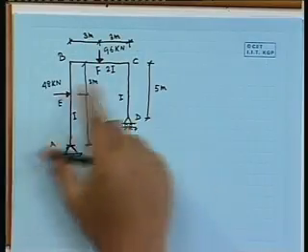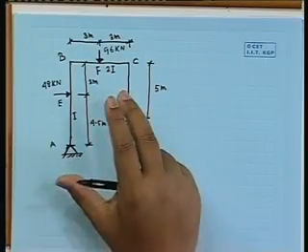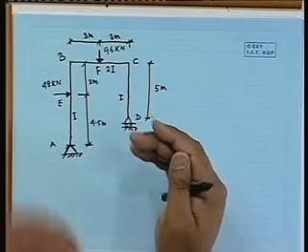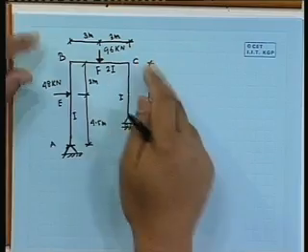Now, I have taken this problem because this problem is little complex compared to the earlier problem. Unit load we have just applied for a beam problem. So, this is a frame with at least 3 members with some loading this side, that side. So, that structure if we pick up, first of all we have to define the different segment, their origin, their limit, plus due to the external load we have to find out the expression of capital M. So, that part we can do, right.